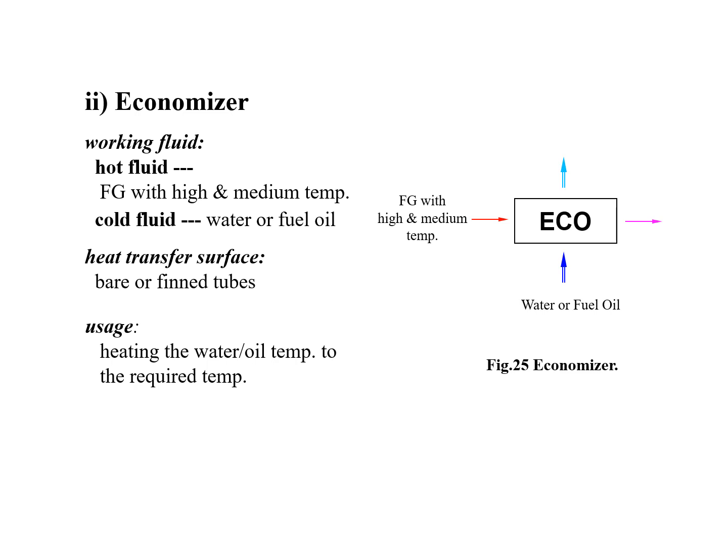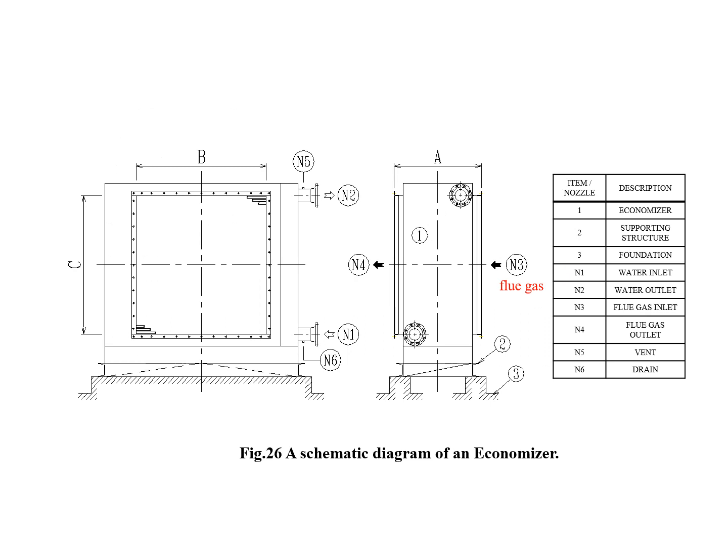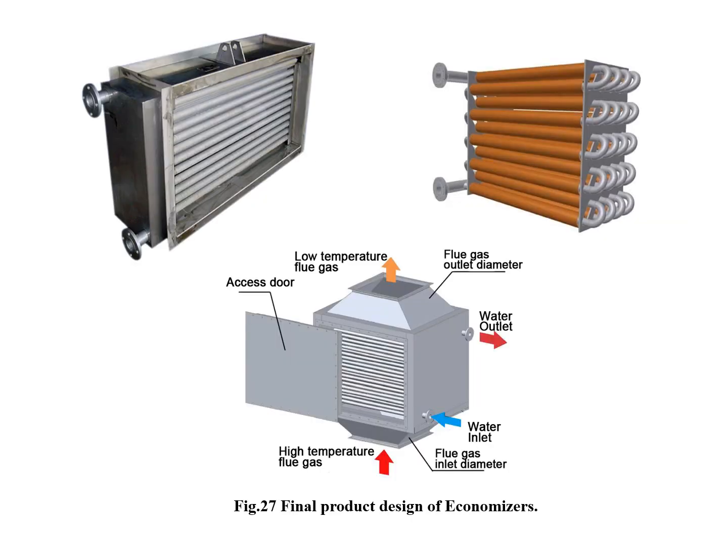Economizer. Economizer comes from the etymology of economy. Economizers are heat exchangers which save energy by using flue gas to preheat a cold liquid. The heat transfer surface is bare or thin tubes. Economizers mostly have a square-shaped design. In addition, they are usually designed in multi-pass, straight pipes with elbows, to increase the time of heat exchange between hot and cold fluids.